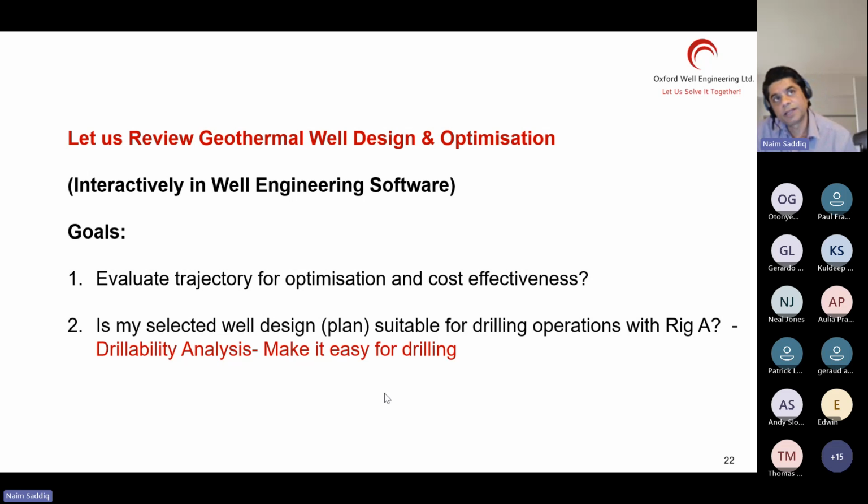Like you said, the well that I have designed had the same problem, by the way. What we ended up doing is this kind of approach. You will do everything just like it is, not like finding the hardest part. For example, suppose you are drilling in a blind area where the pore pressure and the fracture pressure are unknown. And now you have a problem because you cannot design the mud weights. You cannot design all kinds of things. You may want to go for a trajectory that's almost vertical or very close to vertical, less than 25 degrees. So you will design the well according to your challenges that you don't know of or are unsure of.